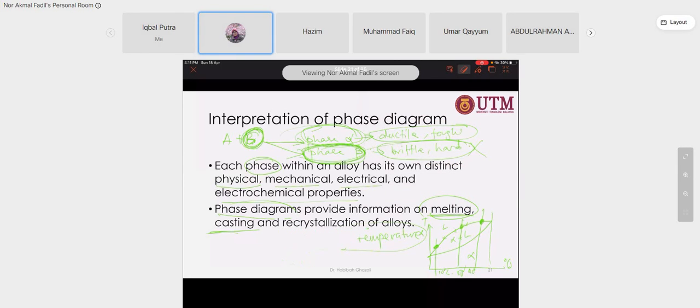So remember this. Okay, so you want to do crystallization, so you have whatever the element composition that you want. Okay, you know the melting temperature. Melting temperature where it starts to form liquid, right? So just now I mentioned about melting temperature. This is not melting temperature. It is the temperature where it completely transforms into liquid. We call it liquidus line. And solidus line is the temperature where it starts to form liquid upon heating.